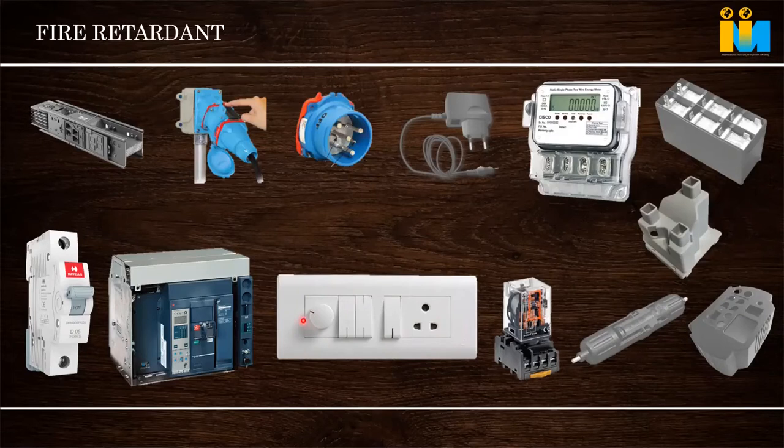And by nature itself polycarbonate can pass the 850 glow wire temperature. But when we add fire retardant, it has the capability to extinguish very quickly. V0 grades are available wherever an electrical conductor is coming. In the switch industry, wherever an electrical conductor is coming, like some connector or plug, they use V0 fire retardant grades, which are higher in flammability rating and quickly turn off the fire.